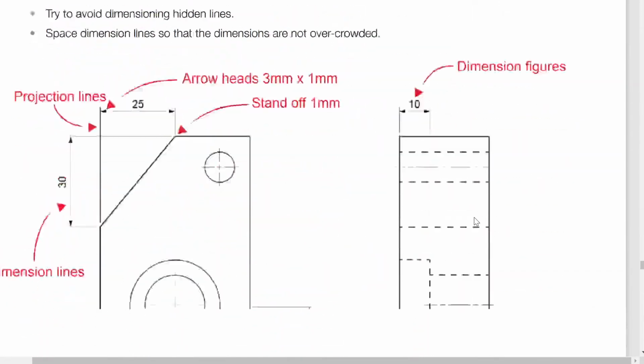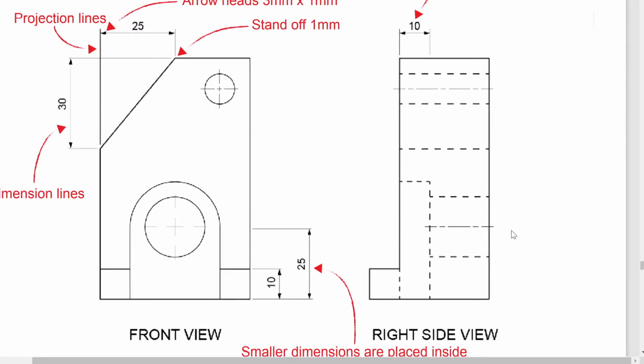Okay, this drawing here demonstrates all of those line types. Here we can see it's in third angle projection because our front view is in the front, and then we have our side view. Now the side view is as though it looks in. So if we see that this is close to the front, this is at the back. That's what we mean when we look at the front view. If you draw those lines at 45 degrees, you shouldn't have any problems, but occasionally people draw things in the wrong spots.